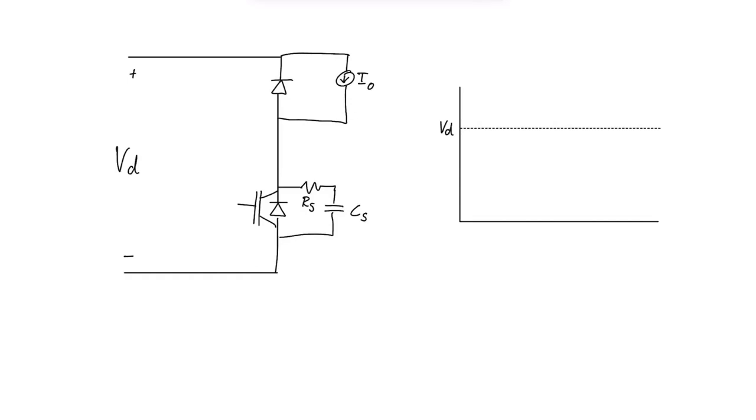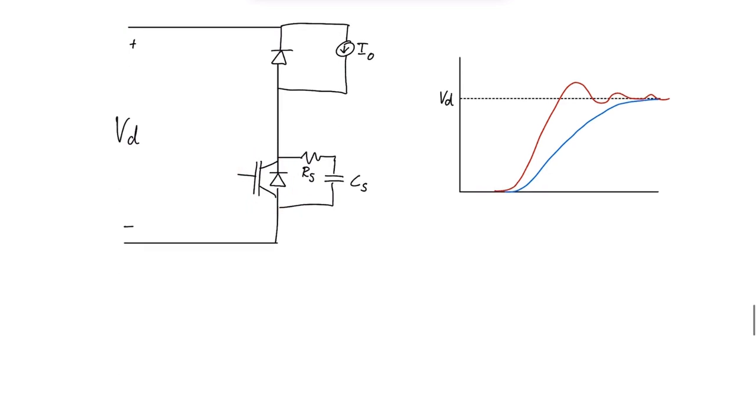So in a step-down converter without a Snubber circuit, the voltage will look like something like this. No, it will oscillate. But if we add a Snubber circuit, we can control the voltage through the IGBT, so it won't oscillate like that. So now I was talking about the voltage in the IGBT right there. And this here is the Snubber circuit which could control the voltage.